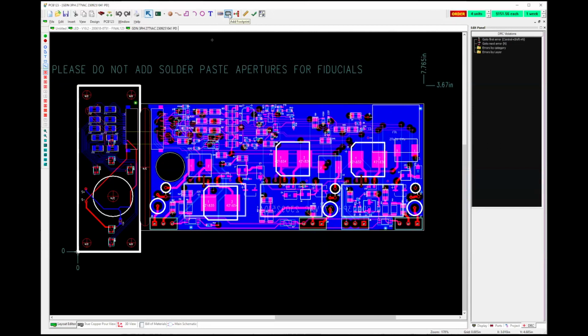It won't be intelligent per the schematic. It's just a footprint. So you'll need to use the schematic function, place an actual component with the part number and all that information attached to it. And a lot of times you'd be surprised, the parts that you're looking for will already be in Snap EDA's library or selection. You can just go search for it and place it that way.